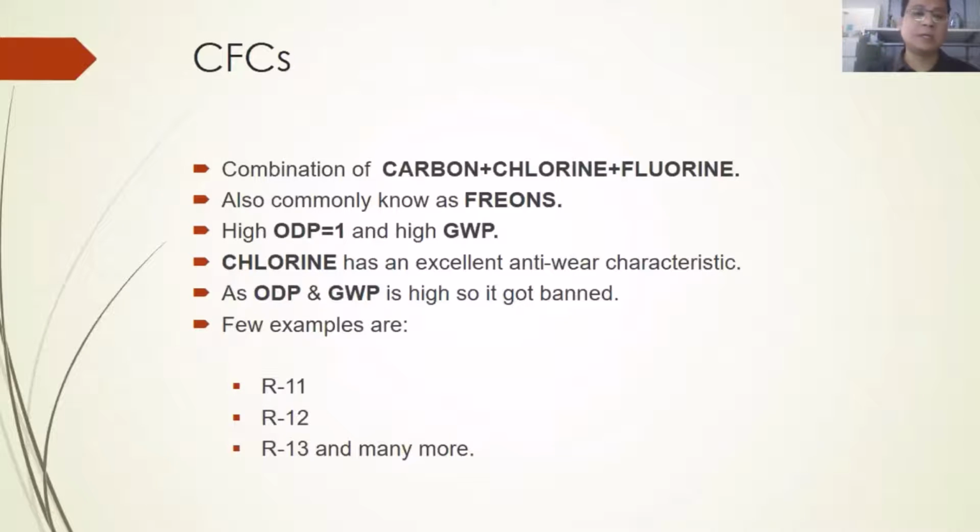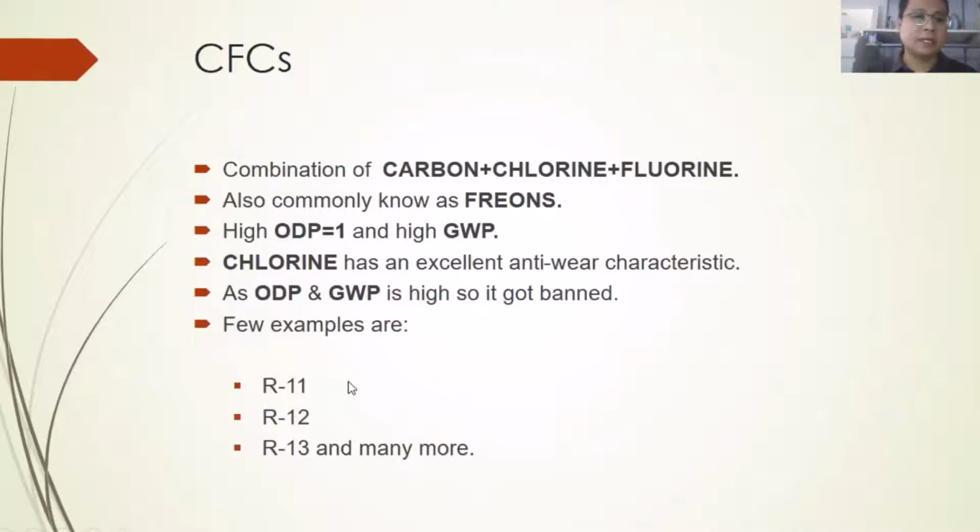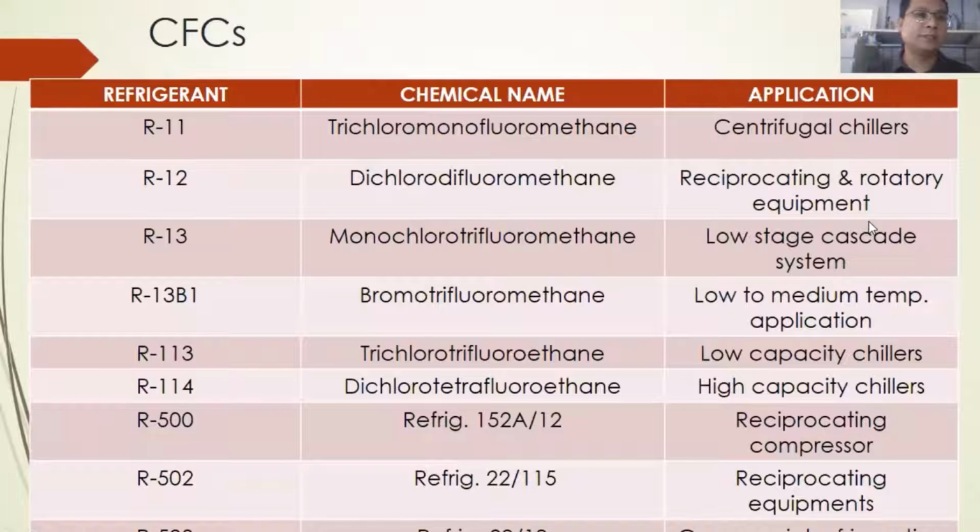Certain compressors work well when we apply CFC refrigerants. But the ODP, ozone depletion potential, and the global warming potential are high, so they have already been banned. R12, R11, and R13. So this is the CFC group, you can see R11, 12, 13, and so on, with the chemical name and the application.